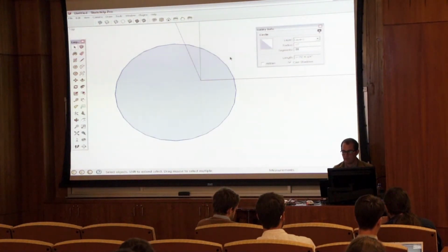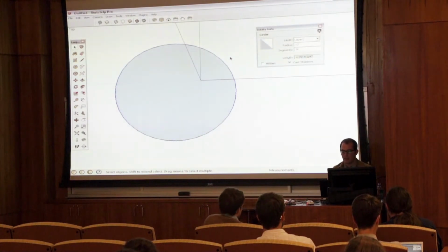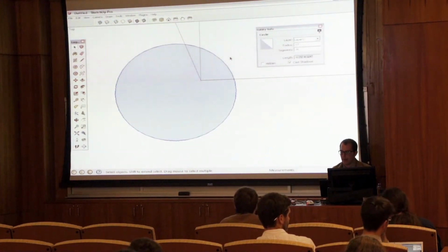For example, if you made this a column and extruded it, you're creating 24 segments on every column. And if you have 20 columns in your model, it can get pretty complex pretty quick. However, in this case, you may want to update this to 36, you might be doing more precise modeling work, and you need a higher precision there.